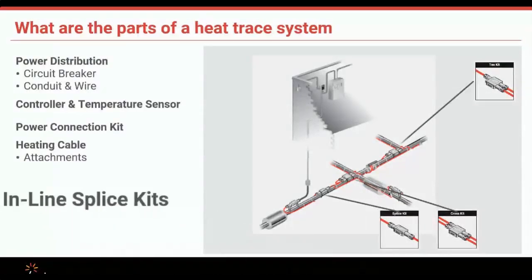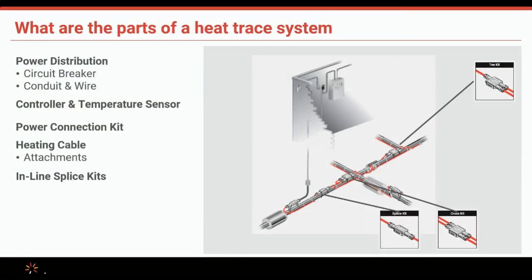Next, we have components. Self-regulating heat trace is a system that is field cuttable, spliceable, teeable. So we have a number of different options for you in the field. If you have questions about what we have to offer, T connections versus splices versus X's, we do have a design guide as well as an online tool that can help along the way, but always feel free to call us and we can work you through that.